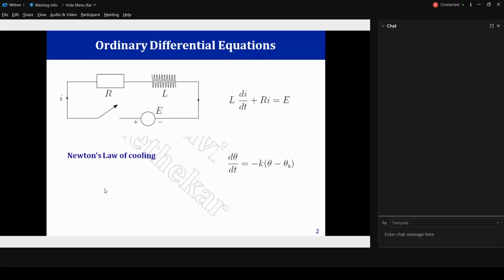If I take the readings from those thermocouples, you will find that the thermocouple at location 1, which is 1 meter from the hotter end, gives some temperature. The thermocouple at location 2, which is 2 meters from the hotter end, gives some other temperature, and so forth. Temperature is decreasing toward the cooler end. So thermocouples 1, 2, 3, 4 have different values. This is my spatial variation.